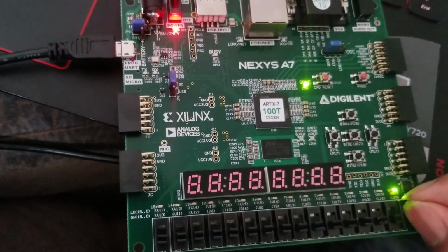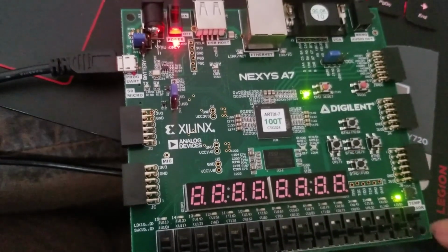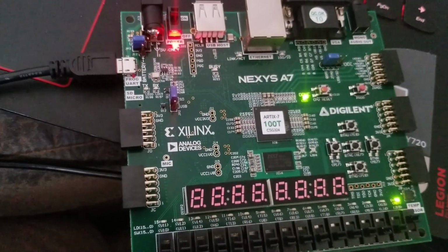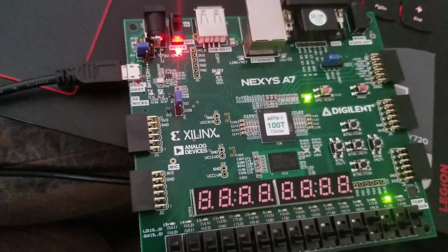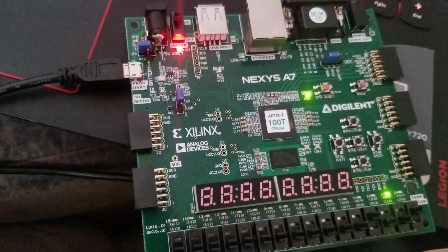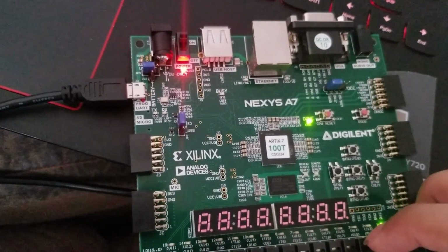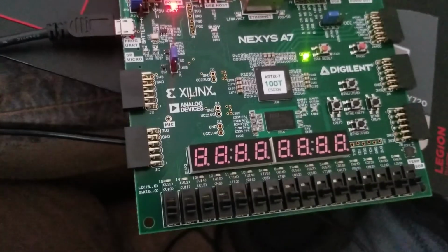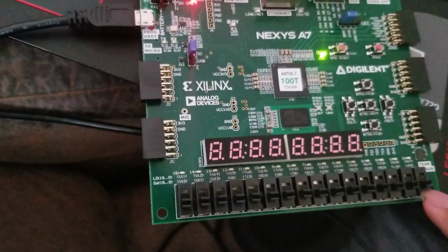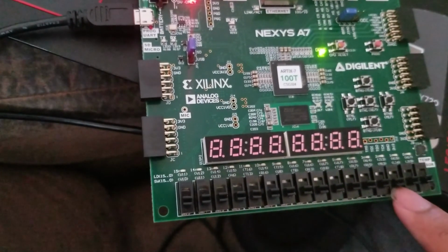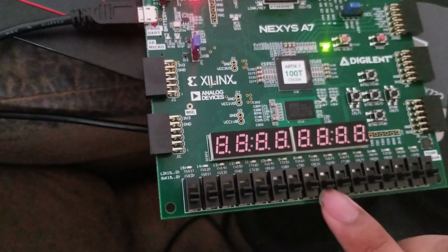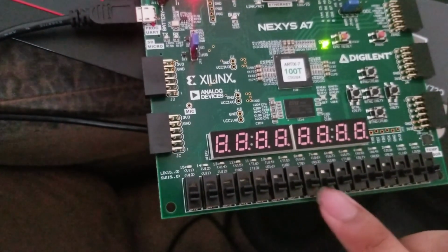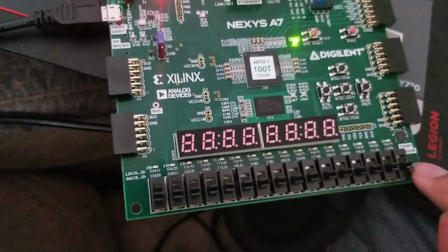So if we were to pull up A0, we get a 1 bit in the first position. And if we were to turn on B1, we would get 2, because 1 plus 1 is 2. So just to quickly reference what each pin means, this is A0, A1, A2. This is B0, B1, B2. This is C in, mode 0 and mode 1. So you just saw that the addition works.